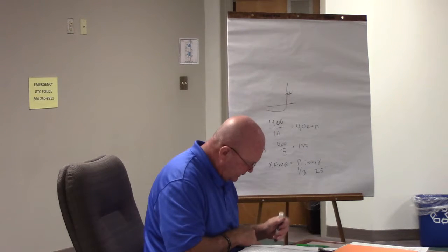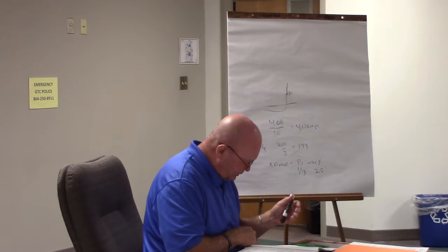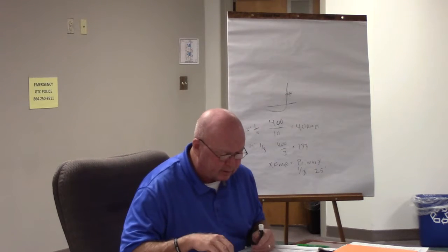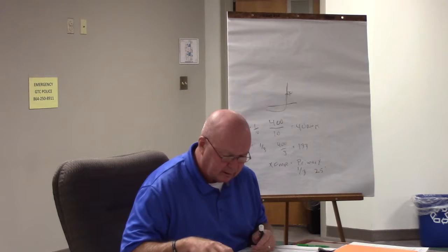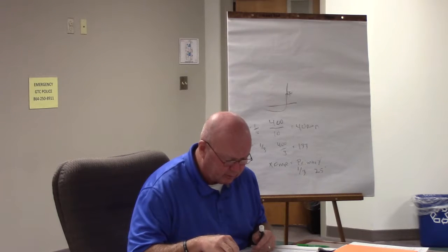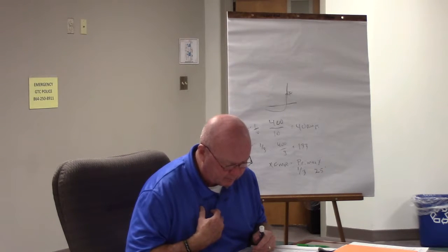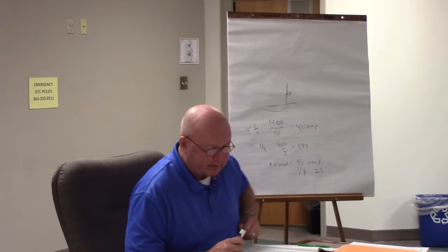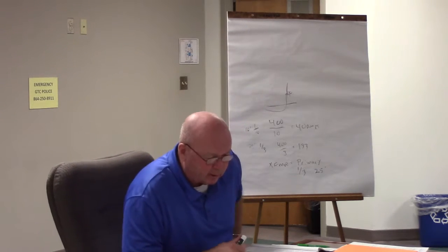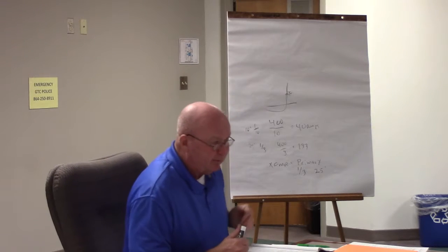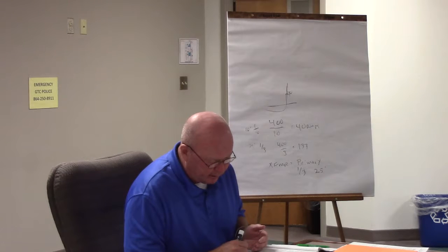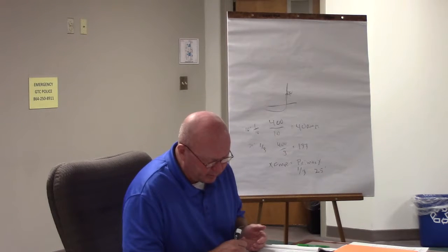Where am I at? We're installed in accordance with 230.6. Now it may tell us, let's look and see what it says, 230.6. Let's turn and see what it says there. We get some few exceptions, like it's installed under the slab. Because if it's under the slab, we're installed not less than 2 inches beneath the building or structure.